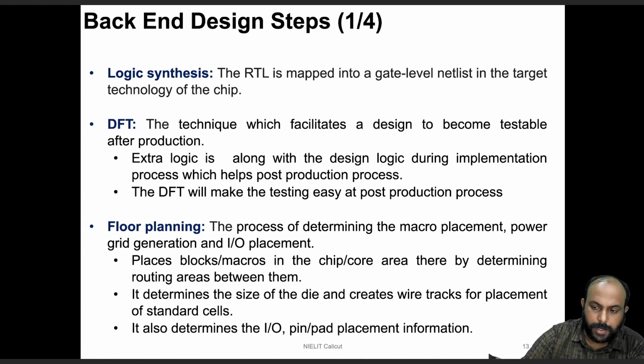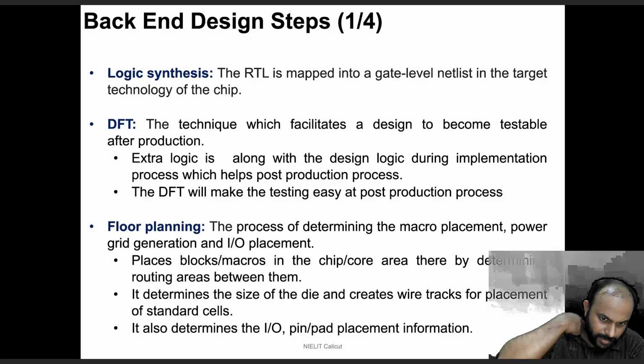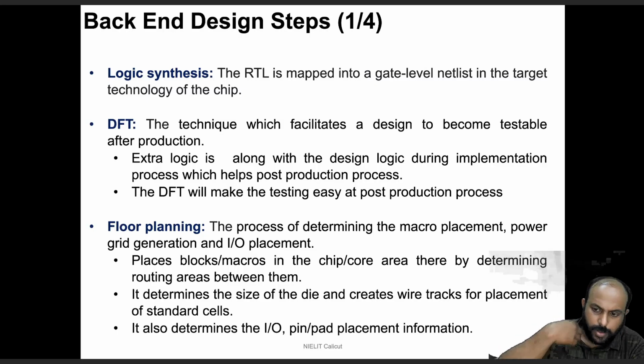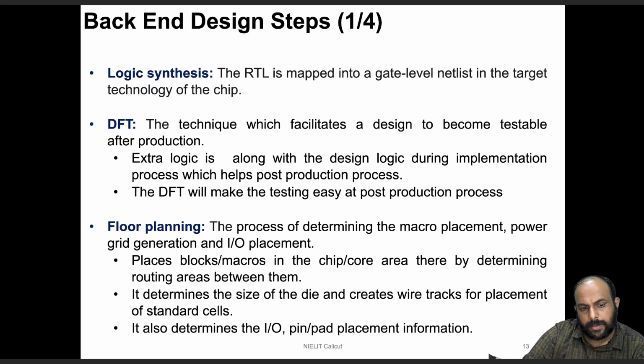So in that arrangement, we also have to plan where the power should be coming in, where should be the exit and entry, and so on. So IO placement, power grid generation, macro placement, everything happens. It's not actual placement, it's about determining where it should be placed. Those steps happen in the floor planning stage.